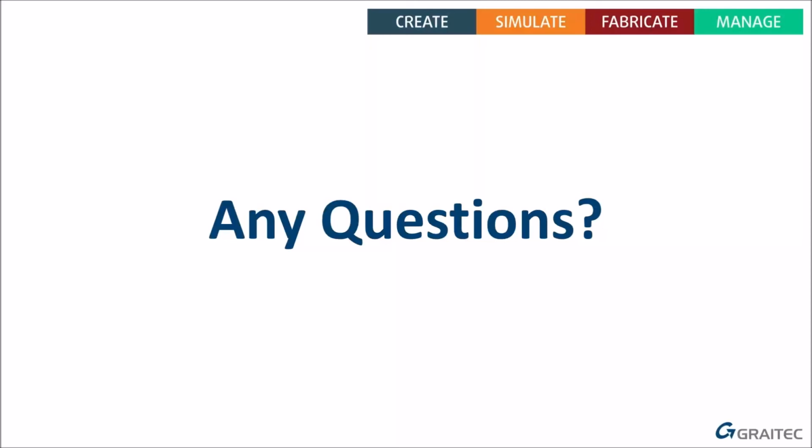So Tim's saying IFC and Advanced Steel don't work great. Tim, Alec has done a webinar on IFC, and why they won't import in some instances, it's all to do with how the data in that IFC file has been created. You can either create it intelligently or you can create it as dumb solids. And if it's done as dumb solids, at the moment you can't import those dumb solids into Advanced Steel. It will only bring in intelligent objects.